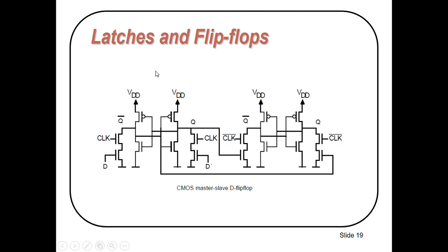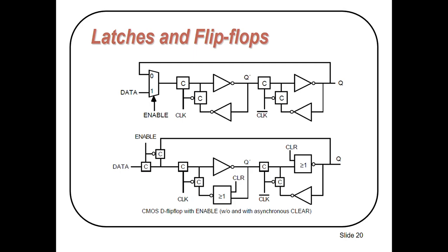You can see when the master is transparent, the slave is on hold, and when the master is on hold, the slave is transparent. So we can design these flip-flop and latch structures by using these techniques.